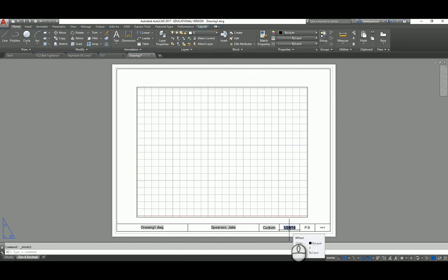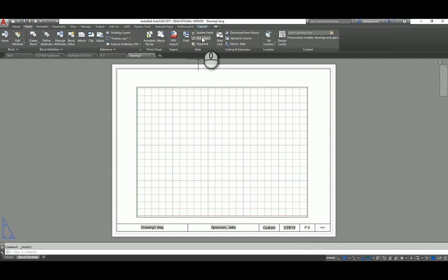Some of you guys, if you have started a new drawing and this date will not update, what you can simply do is go under Insert, select Update Field, select it, and if the day is new and it has not updated, select Update or Update Field, select the text, hit Enter. It will fix itself. So let's go over an example by doing the custom one.